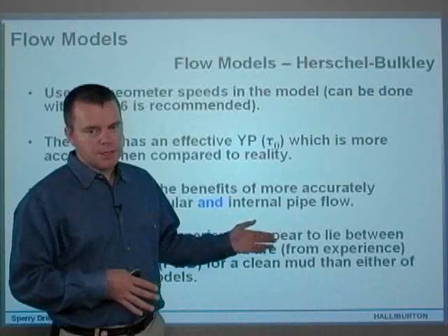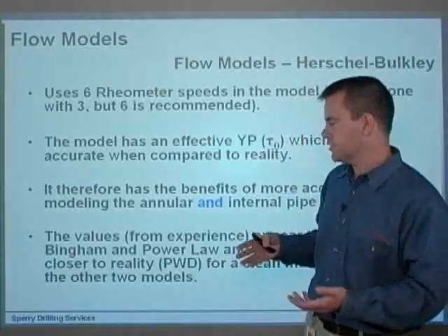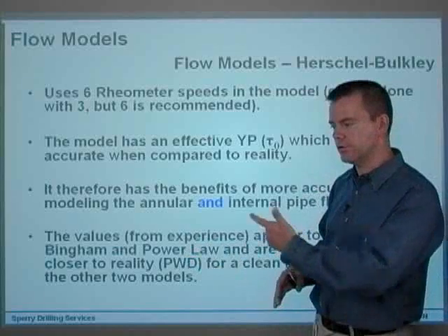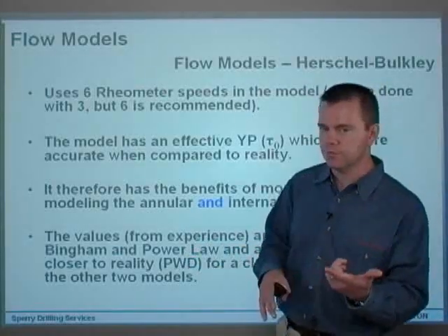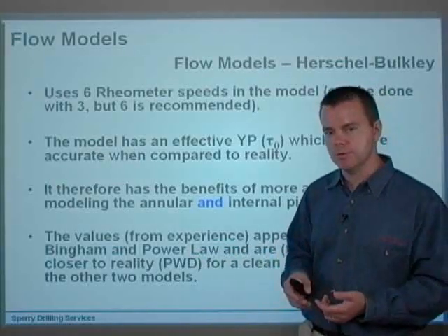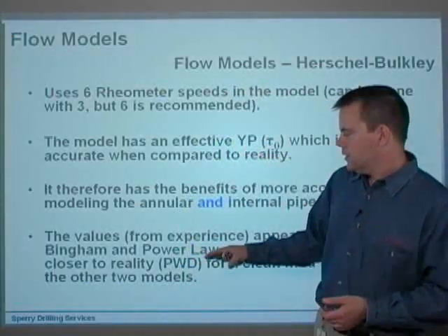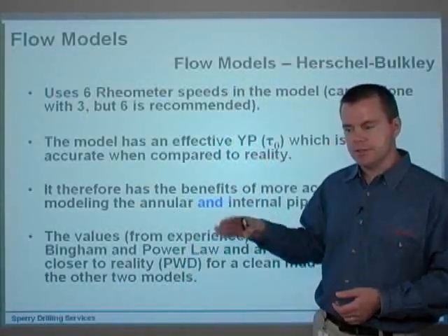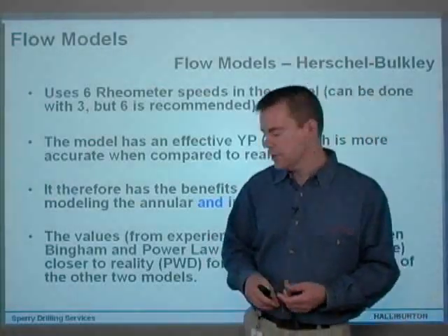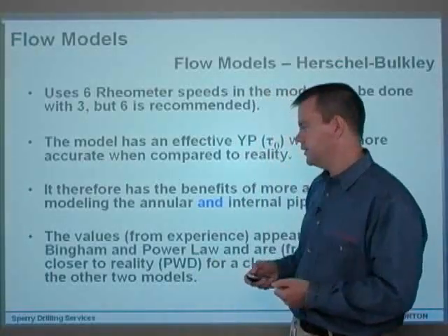If it isn't in your case, if for some reason the model isn't describing reality very well, then I would suggest it's not because you should be using Bingham or you should be using power law. You shouldn't be using either of those at all. You should continue to use Herschel-Bulkley. But I would actually look at some of the inputs that you put in. Usually it's a geometry thing or something like that that's causing a difference between reality and the model's prediction. However, there are also some other things like temperature and pressure effects which can cause a difference as well.